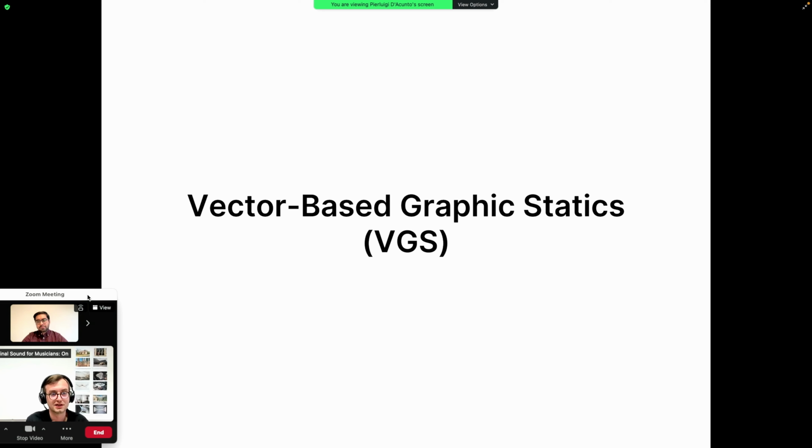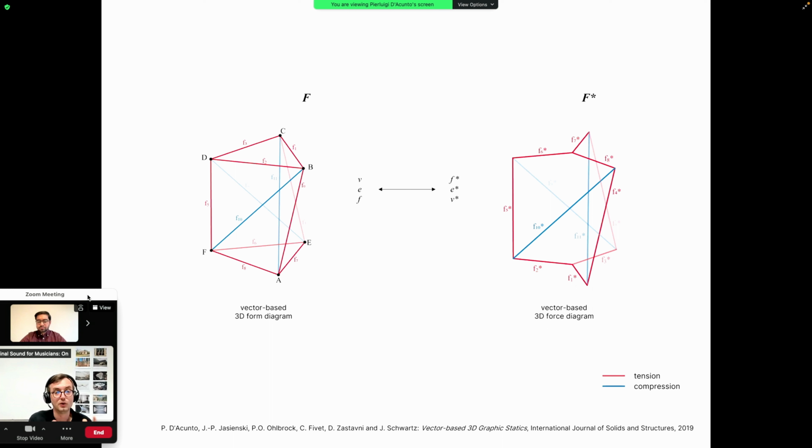For every transformation of a structure, it was necessary to rebuild manually all the form and force diagram. This is brought into a computational setting that allows real-time operative transformations on the form and force diagram. And on top of this, thanks to the use of a three-dimensional software environment, it is possible to bring all the construction from 2D to 3D.